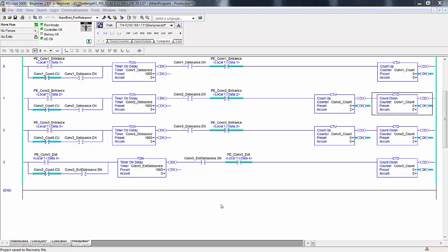Out of all of this should emerge a functional specification. You see, as the engineers and the designers are going along, they're taking notes and writing down everything that they need. And at this point, because they are recognizing what specific sensors and actuators they need and making note of them, making note of the length and the definition, they are coming up with a functional specification that the controls engineer can then use to design the control system, selecting motor drives, motor starters, pneumatic hydraulic valve banks, power distribution, circuit protection, the specific controller, I/O modules, I/O interfaces, and of course HMIs, whether those HMIs are push buttons and lights, touch screens, membrane keypads, etc.